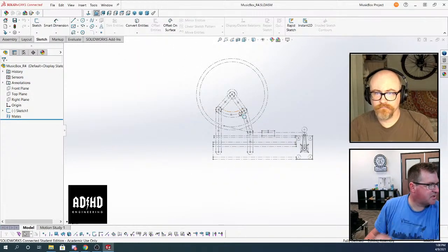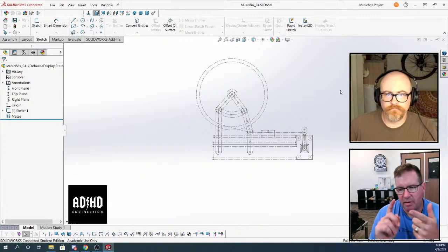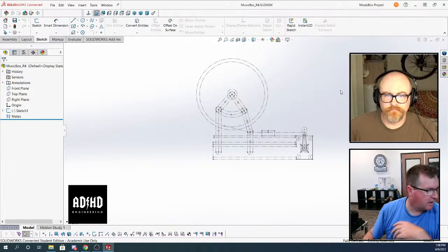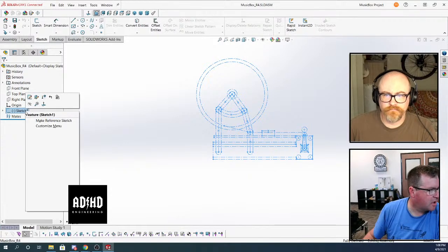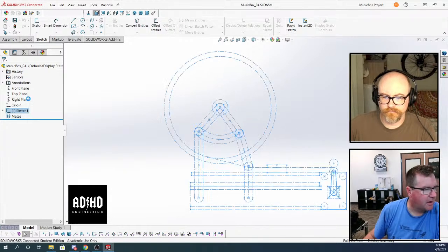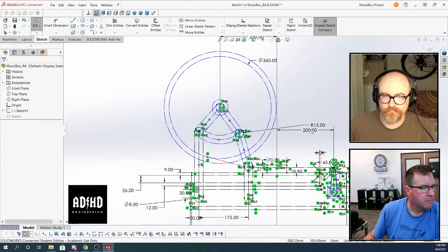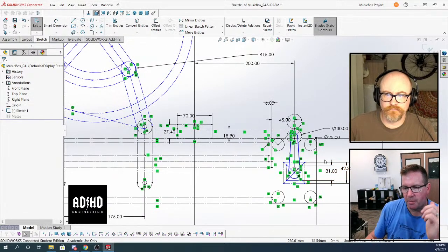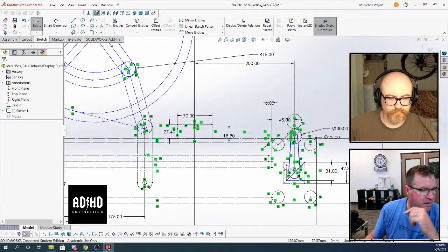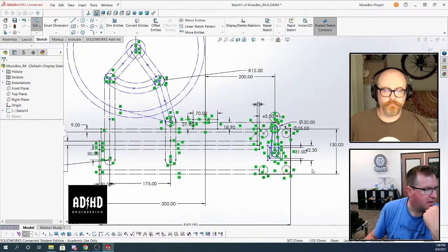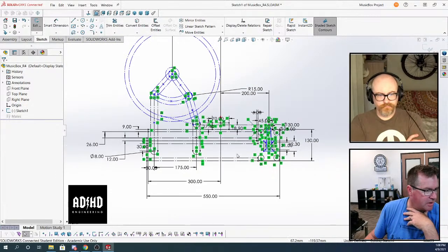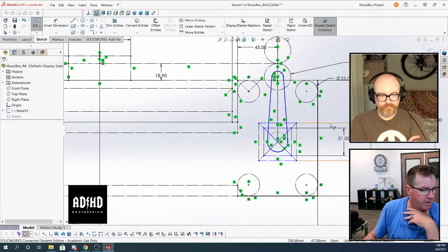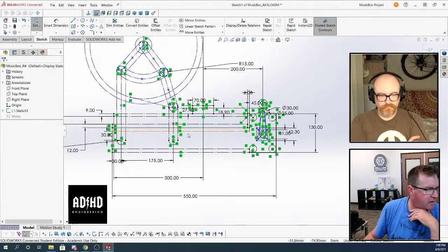So this is, before we did this with the layout and we did it with blocks, I did this last night just as a single sketch for the sake of getting something on board. And actually, David, I think I know what the problem was why we couldn't do a belt. I'll get to that. But essentially, I just laid it out all as one sketch. And I was able to put in the motors. There's more dimensions here than are absolutely necessary.